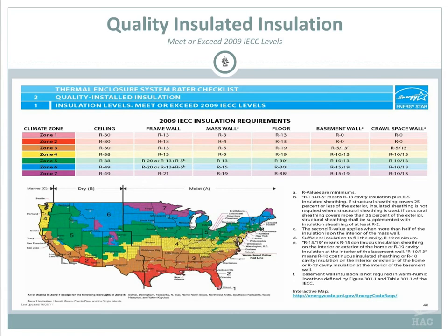Again, mass walls. When we did our adobe wall, we're in Zone 3. We did mass walls, 18-inch block adobes at 1 inch per R value. So we got an 18-inch block, and then we put an R10 foam board around the outside, and then we wrapped it, black paper, stucco. By the time we finished, we had about an R28, R30 on that wall. So, different ways of getting there, but these are the minimum requirements.